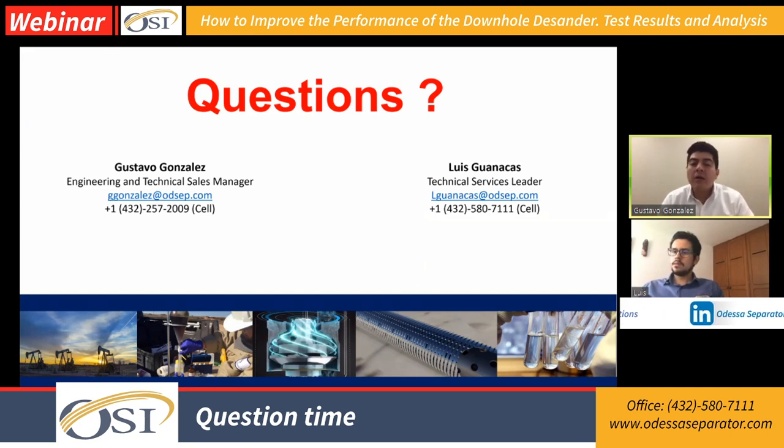If there is a new well, I would recommend going with a better alloy to be more resistant to erosion and abrasion, because normally if it's a new well and you're completing with ESP, you're going to see more changes in the ranges. Like we mentioned before, from 5,000 you're coming back to 3,000, and the changes are so drastic that you can generate too much centrifugal force and cut the desander.